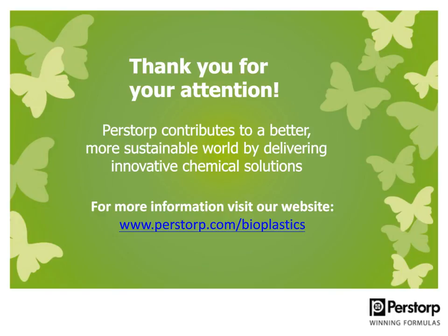The first one I'm going to go to is, what is the compatibility of caprolactone with starch polymers? It has a good compatibility with thermoplastic starch, and you can blend it in various ranges of PCL from 20% up to 50%, really depending on your application and the properties that you're targeting. So it has a good compatibility.